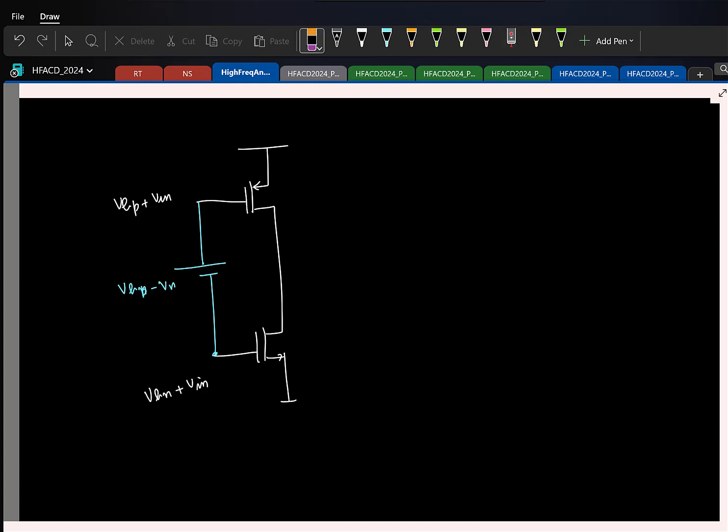In principle, you have what is called a floating battery. I'm calling it a floating battery because both the positive and the negative terminals of this battery are accessible to you. Typically with DC sources, the negative is grounded and you don't have access to the negative terminal, but in this application we need something like this. We don't have a real voltage source like this, so can you think of some way in which I can get a voltage drop across two points?